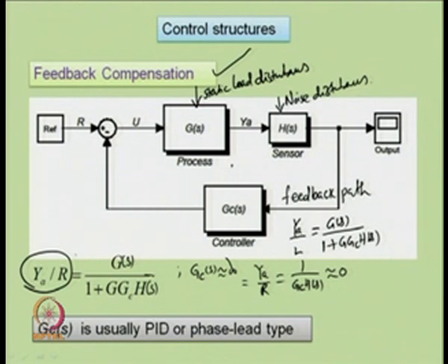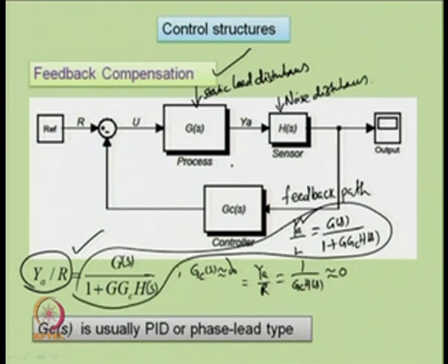If you look carefully, the transfer function with respect to the reference input and the transfer function with respect to the static load disturbance input are the same, thus facilitating one to design a controller conveniently, because the two closed loop transfer functions are equal. So, the same technique or same criteria may be used to design the controller G c s, whereas for the series compensation scheme that is not the case.